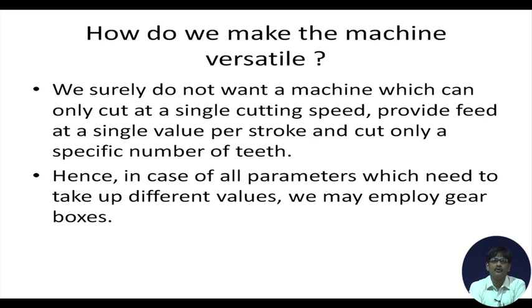You can employ any cutting speed, say within the range of 30 meters per minute to 150 meters per minute. Generally, instead of cutting speed, we employ strokes per minute, which means you can use say 30 strokes per minute, or 300 strokes per minute, like that. With the strokes per minute, the cutting speed will increase.